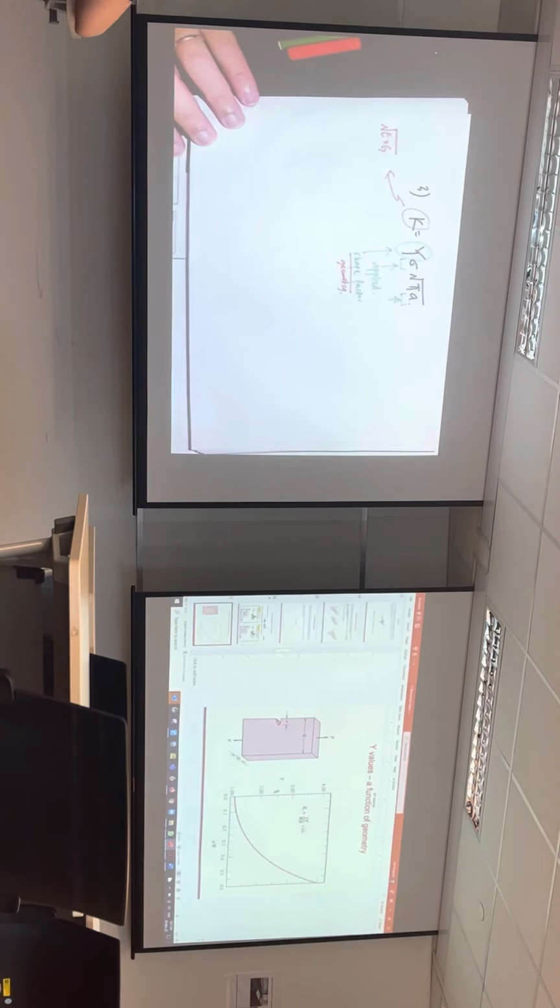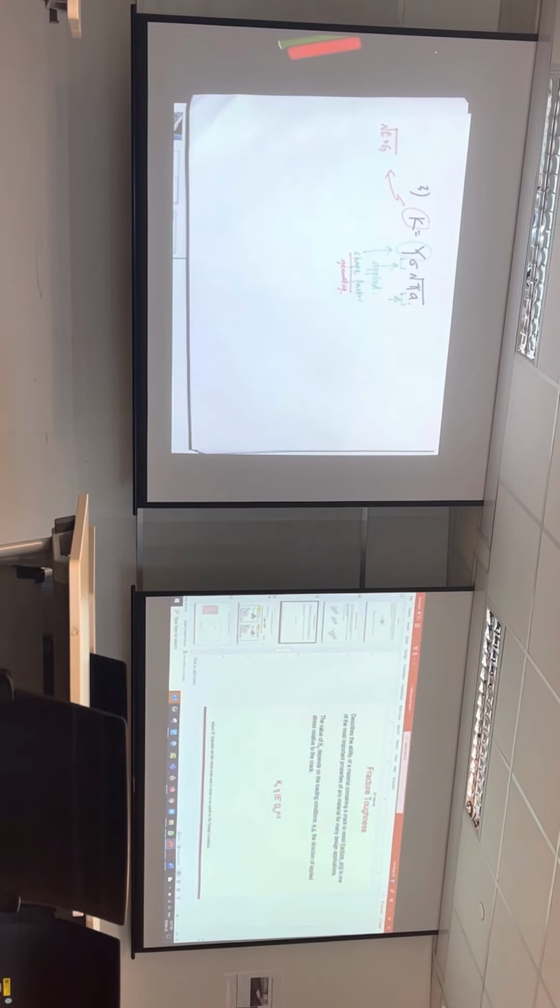So fracture toughness, if you go to fracture toughness, there are a few modes which we are talking about, the mode 1, the mode 2, and the mode 3. In this particular course, we are only focusing on mode 1. Mode 1, because this is more of opening up, we are not doing the shearing or the tearing kind of values.